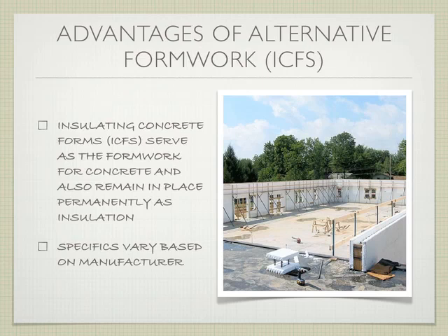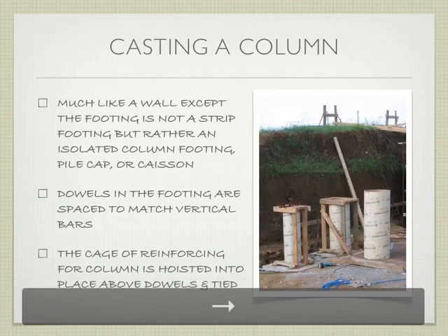Generally speaking, while with the plywood formwork we were able to pour a full story in one lift, for something like this we may be stuck pouring a building in 2 different lifts. So we might have to pour the bottom 4 feet followed by the top 4 feet, because the pressure of the concrete in these walls may blow out. This will vary depending on the manufacturer and the type of concrete used, but it's important to understand.